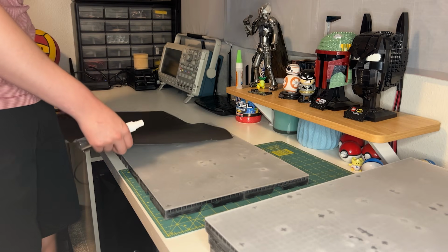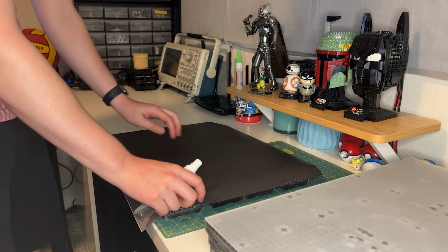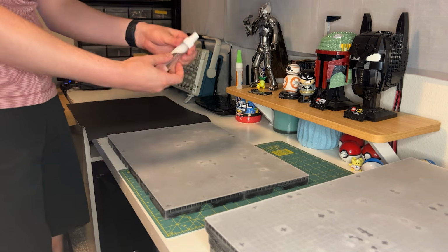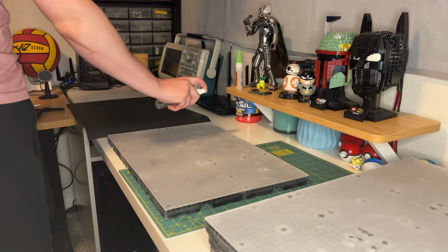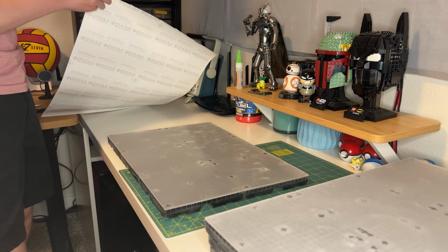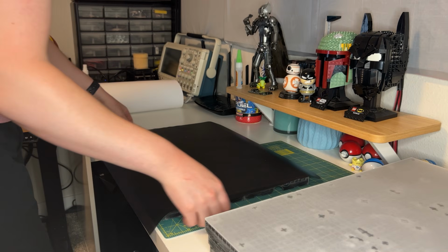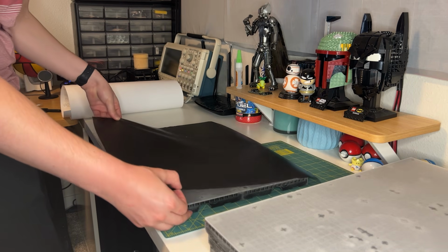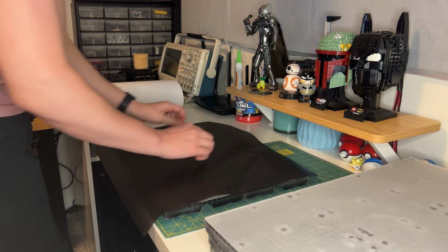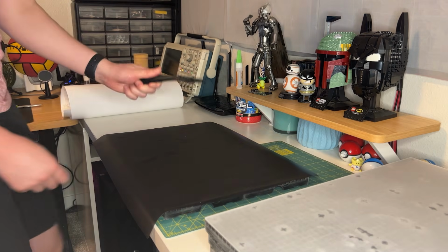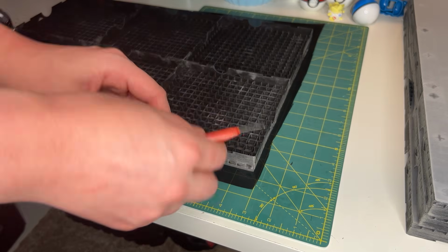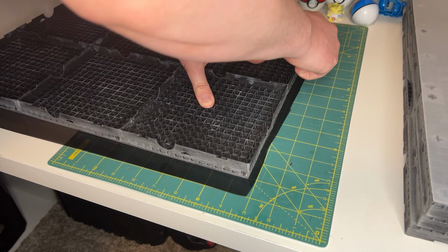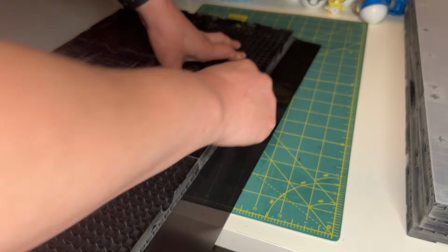I've got this section that I've trimmed off that's just a little bit bigger than my panel here, and I have this mixture of water with a tiny bit of soap in it. So the first step is to just get this nice and wet. All right, then I'm gonna lay the tint over the top. That soapy water will keep it slick so it doesn't just stick down immediately. Okay, and then I'm gonna use this squeegee to get all the air bubbles out. And then the last step is to take this little knife and trim off all of the excess. There we have it. Nice matte black panel.